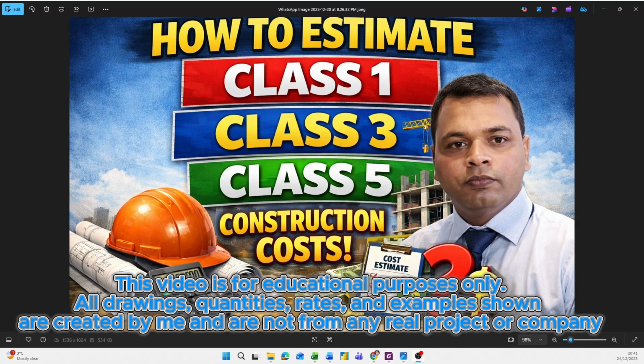When do we use a class 3 estimate? A class 3 estimate is used when the project needs to move forward, but the design still needs more time. Many times the project needs to go to tender to hire a contractor, but the final design is not finished yet. So contractor selection and the final design are done at the same time. The class 3 estimate helps the owner decide the budget and select the contractor while the design continues.